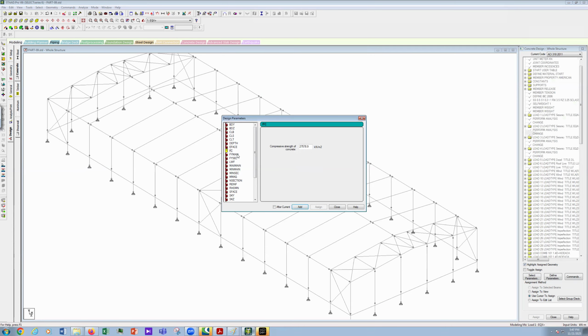Then you can go for FY main. This is for the yield strength of reinforcement. This is 60 KSI, so you can add this one, and this is for your secondary, that means tie or stirrup. You can also add this one. We'll keep this one, and then you just need to assign our clear cover. As you know, for a column below grade, the clear cover will be more, say 65. This one is also 65. This is the clear cover for side, and this is for top.